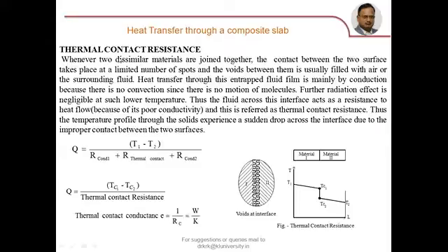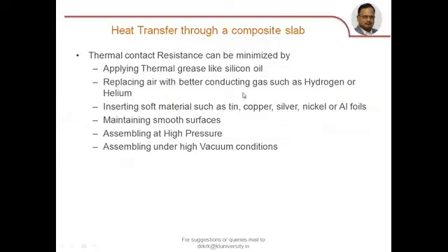The problem will be there even for similar materials also, but normally when we have similar materials, we don't go for joining them. We can even have an integral one. So what are the points with reference to this thermal contact resistance? You can minimize this thermal contact resistance by applying a thermal grease like silicone oil, or replacing air with better conducting gas such as hydrogen or helium.